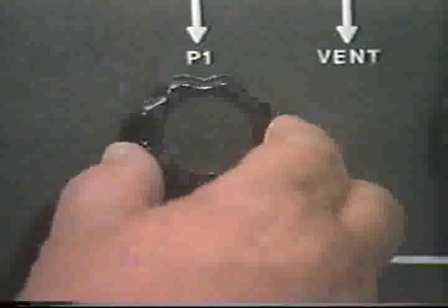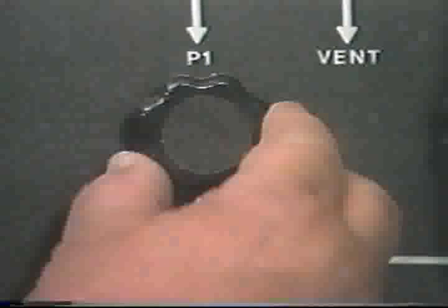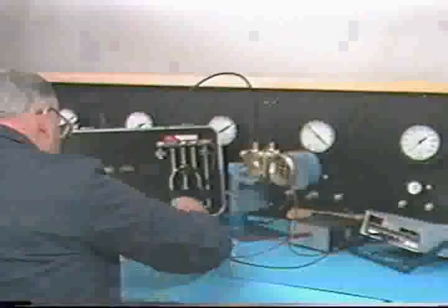Once the zero has been adjusted, you can begin a 5-point check to the high side using a second regulator. Remember, the 5 test points you'll use for calibrating the instrument represent the 10, 30, 50, 70, and 90% of span, adjusted for specific gravity. Complete the calibration procedure as you would for any differential pressure transmitter. Make a 5-point check, determine the instrument's accuracy, and identify and correct any errors. Then make verification checks and any further adjustments.